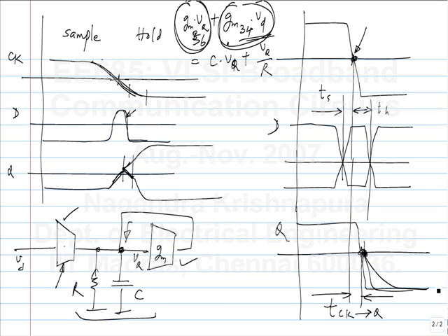Any questions? Did everyone understand this discussion of how each of these affects the parameters of the flip-flop? It is a kind of qualitative discussion, but you can get a quantitative idea by estimating the GM of each of these pairs. But also you should keep in mind that it's heavily nonlinear. Once the differential voltage goes beyond a few tens of millivolts, the effect is nonlinear. The differential pair becomes nonlinear. So you also have to use simulation, but you can use these guidelines to go in the right direction while optimizing the flip-flop.